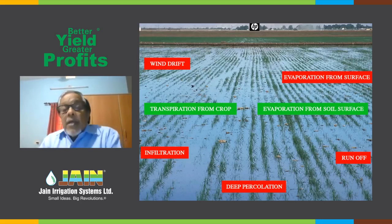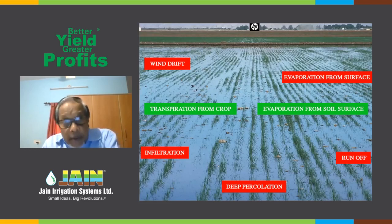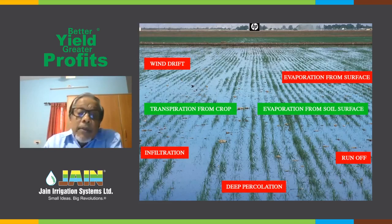What has been happening is that in flow irrigation, and even in the furrow irrigation which we saw previously, the components of water in the red, the water loss from the field, were far higher than the fraction of the transpiration or the evaporation from the soil surface. In other words, the plant used water became a smaller fraction than the water which goes either into the air, or deep into the soil, or to the next field by lateral movement or seepage. These volumes have no accounting.